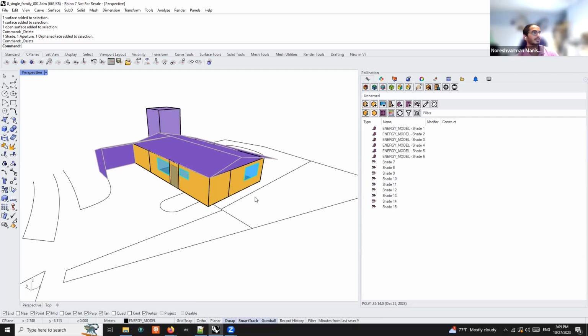Yeah, I was thinking that, okay. That louver thing is basically what it does. You can have as many louvers as you want on a window. And the EnergyPlus blind material is exposed in Rhino, so you can create a window construction that has a blind material, and that will simulate much faster than all those little detailed geometries. Got it. Thank you.